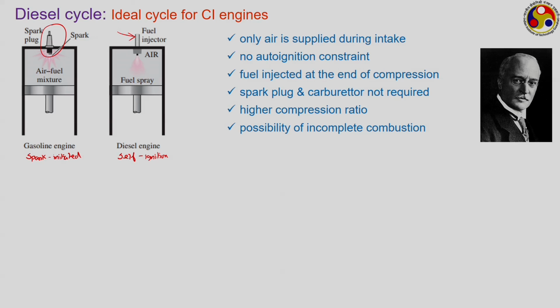But one drawback here is the possibility of incomplete combustion, because in case of SI engine, the fuel and air are uniformly mixed in the carburetor before supplying to the cylinder. So, every fuel molecule generally has a sufficient number of air molecules around it, but here in diesel engine, as the fuel is being sprayed inside, it is very much possible that some of the fuel droplets may get sufficient amount of oxygen in the neighborhood and some of the droplets may not get any. So, it is possible some amount of fuel may remain unburned, leading to incomplete combustion, loss of fuel and subsequent pollution problems, which is not that significant for SI engines.